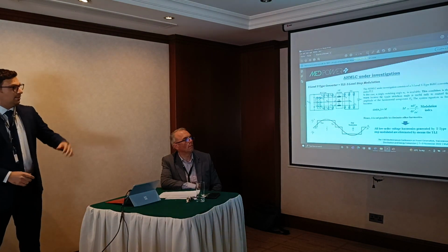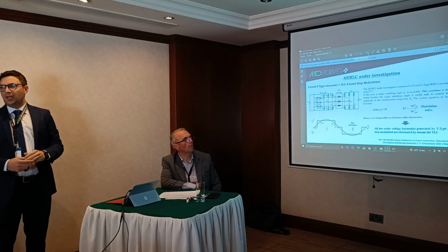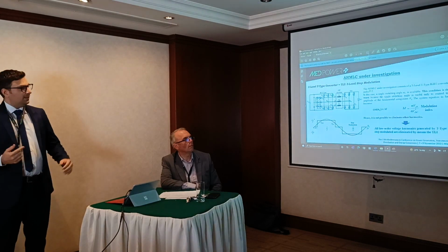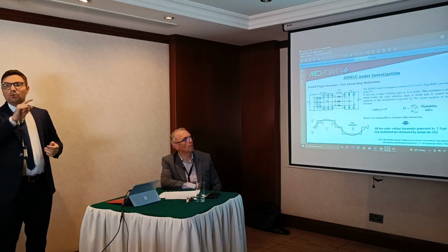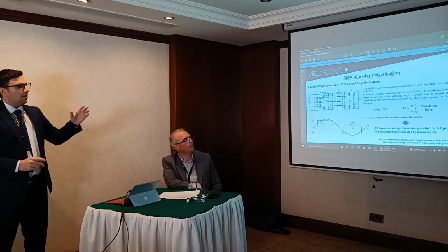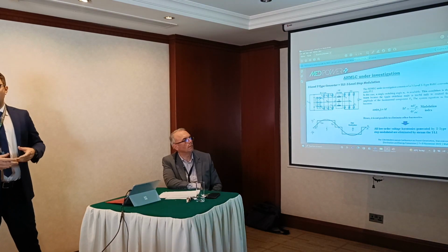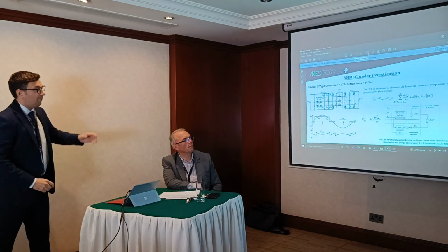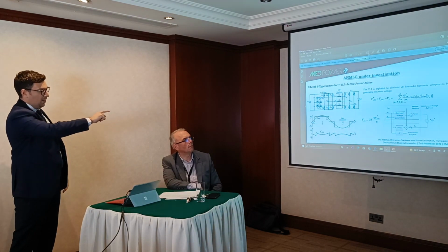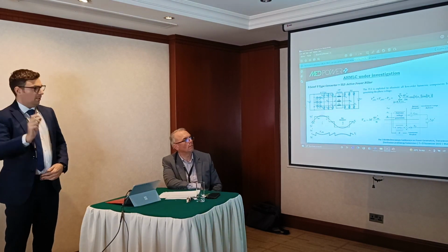In the asymmetric hybrid multilevel converter under investigation, the worst case is when the main multilevel converter is at three levels, because in this case we have only one switching angle, which is used only to regulate the fundamental component. So it is not possible to eliminate the other harmonics. For this reason, the use of the two-level converter becomes very crucial, because if we set the reference voltage of the active power filter as the difference between the step waveform minus the fundamental component, it's possible to eliminate harmonics on the phase voltage of the machine.